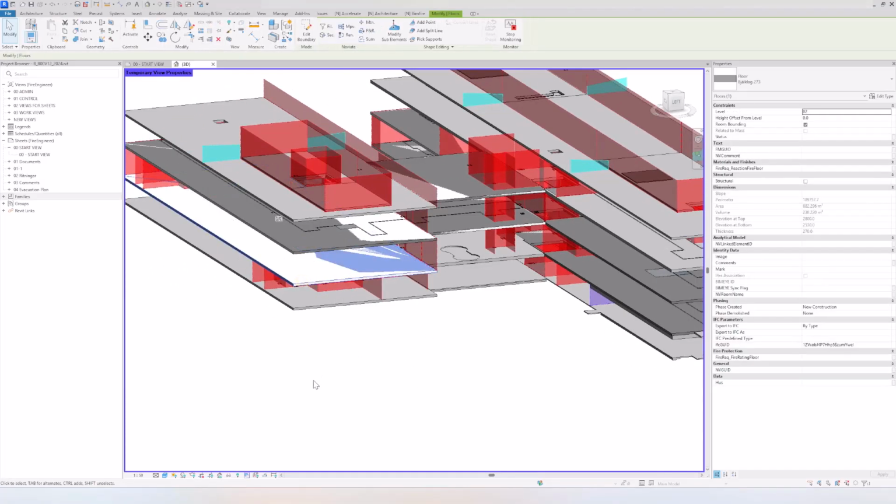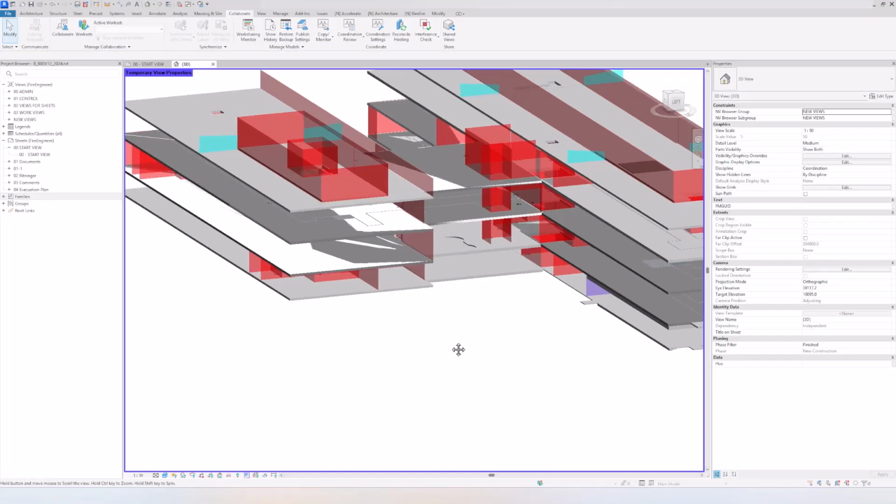I'm going to start with this one. So you can see here it says floor 273, but it's actually a 270 floor. And what's happening when Revit's copying those floors into our model, it kind of makes mistakes, to be honest. And that is because they are not completely the same in layout and different cuts. So if I select the floor up here, it's called 274, still 270. This means that for every 270 floor, it added a value on the different ones, even though they are the completely same floor. We're going to adjust this later. We're going to fix this globally, so to speak.